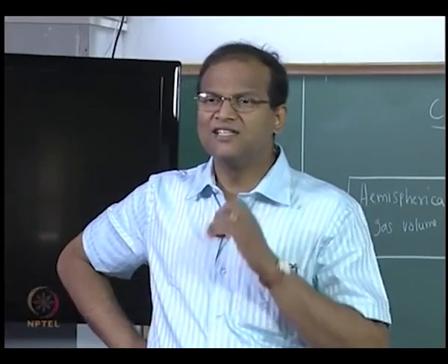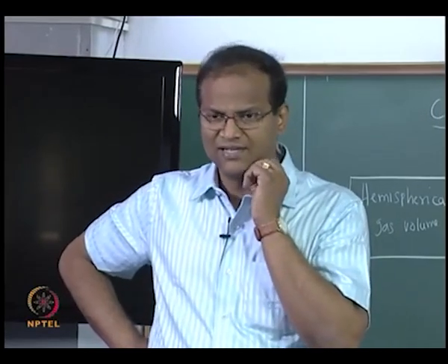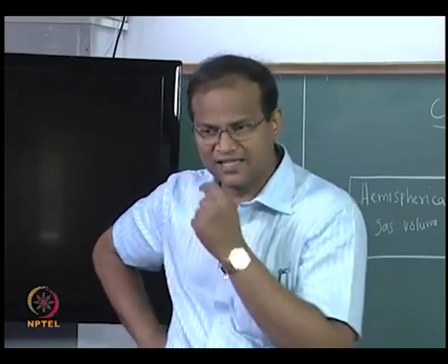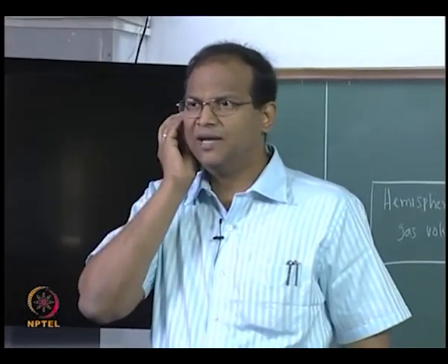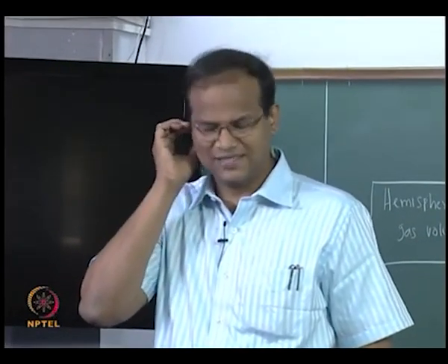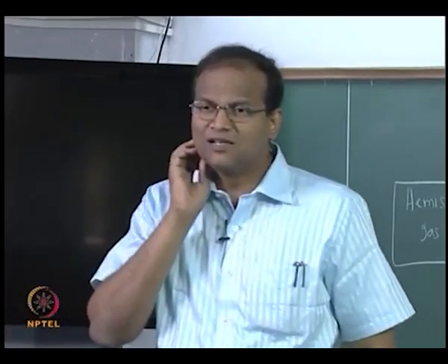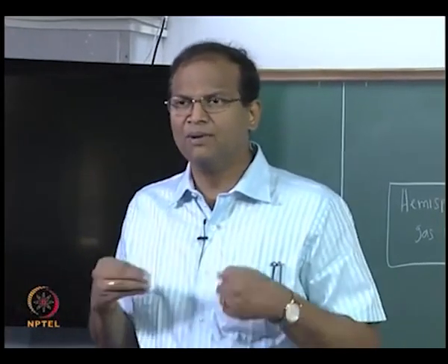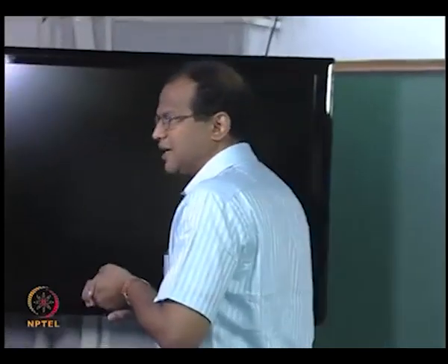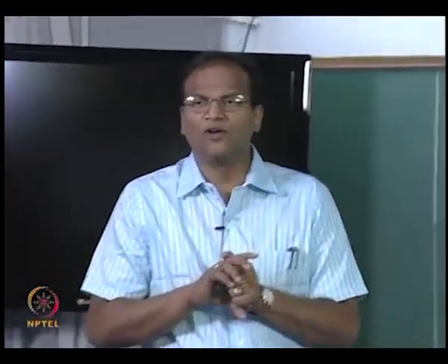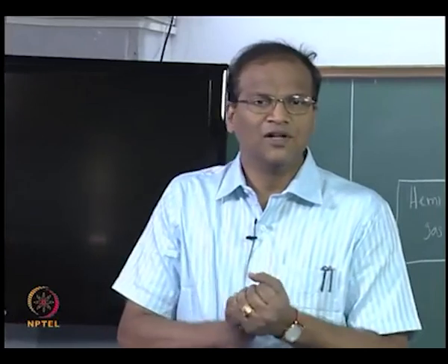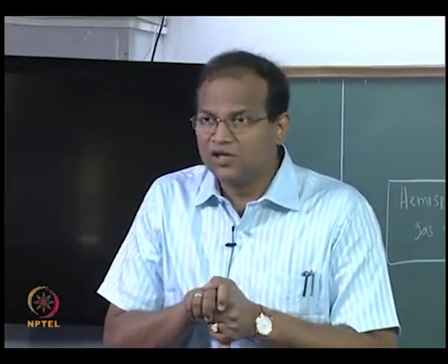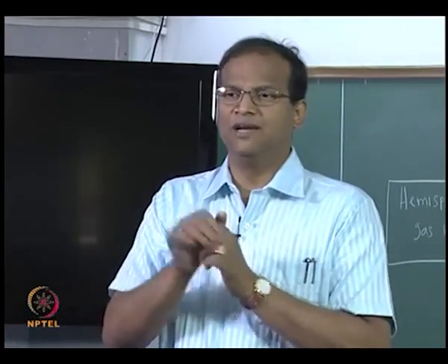The mean beam length is a concept wherein we are looking at the average distance travelled by the rays when passing through this participating gas before arriving at a particular area dA. So in the first part of today's lecture we will elaborate on this concept of mean beam length. We will try to figure out what this exactly means, and then for a general case, how do you get the mean beam length, because the mean beam length, as you will see shortly in today's class, will be the starting point for your analysis of radiative heat transfer in enclosures which contain an absorbing and emitting gas.